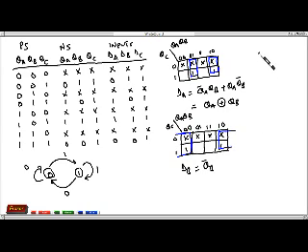Then finally for DC, we can observe that the K-map will be a K-map filled with don't cares and ones. So if we were to group all of them, then that would mean our DC is a 1. And these are the inputs to the 3 flip-flops that will help us design the counter for odd numbers between 0 and 7. We proceed to simulate these.